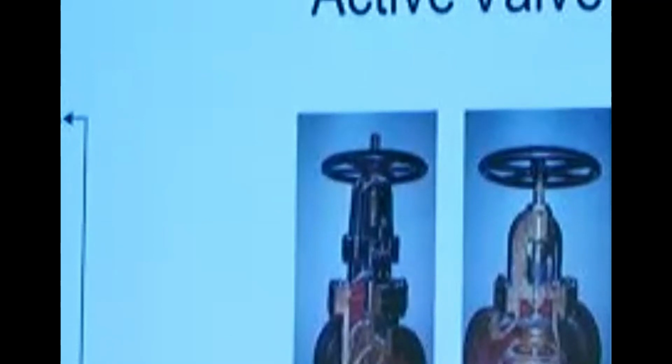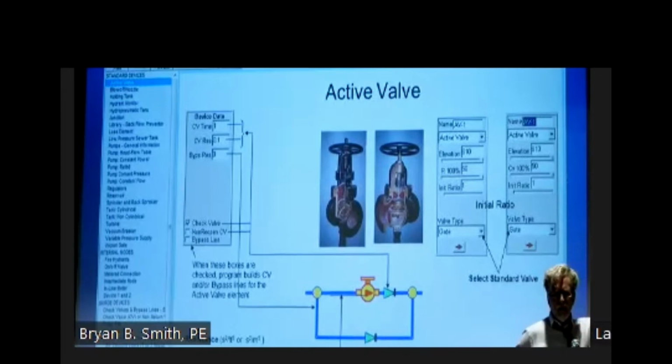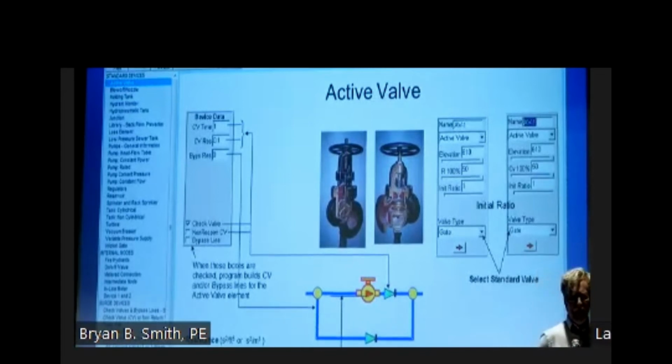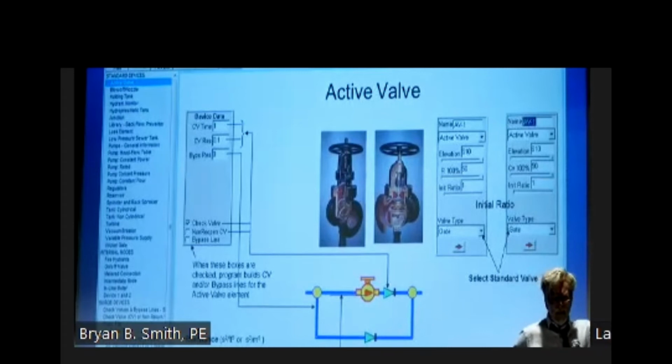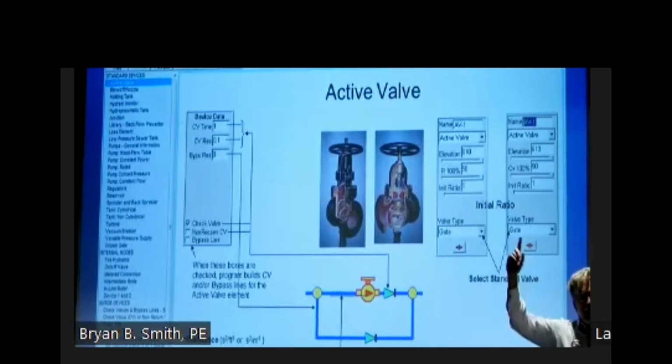So you've designed a perfect pump station, pipeline, everything is beautiful, steady state is fine. And unless you're looking at pressure transients coming back at you at 100 times a second, you're like, best design ever, right? And then down the street here, there's that really big building and they have a reduced pressure backflow assembly. And then there's a detector check. And every month they test their fire water system, or that chemical plant over here.